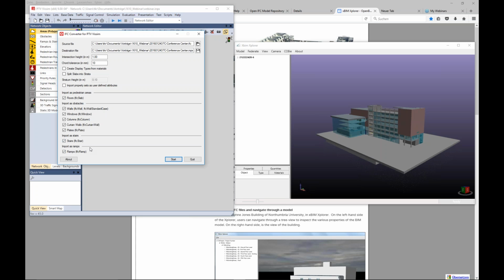The last time we checked, that was half a year ago, escalators were not a specific object in IFC. They did not exist. So it's just a matter of the definition of the open BIM IFC standard. What does not exist there, we cannot import. It probably is modeled as a stair then.